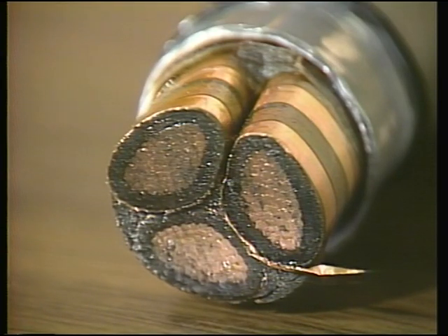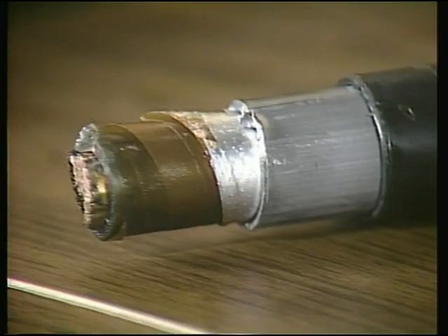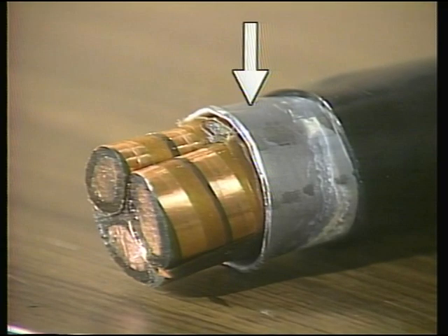With some cable designs, like this 3-conductor cable, there may also be a metallic shield in the form of a tape ribbon. On other cables, the lead cover serves as the metallic shield. Because the paper insulation is vulnerable to damage caused by water or corrosives, the cable is enclosed or jacketed with lead. The lead covering is flexible to allow it to be bent during installation, and it's very effective in preventing damage to the paper insulation.